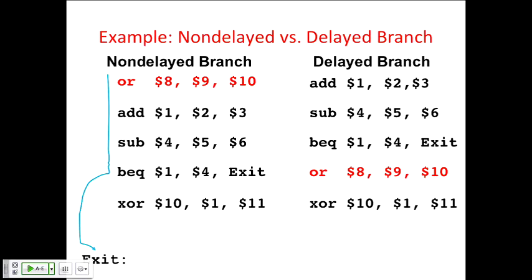It just magically disappeared. There's no hardware. The hardware is very simple because it's not doing anything. I just redefined the software interface to make the hardware's life easy, right? So this is actually what's in MIPS. So MIPS has this delayed branch. And in fact, a lot of the early RISC machines had this delayed branch instruction in.